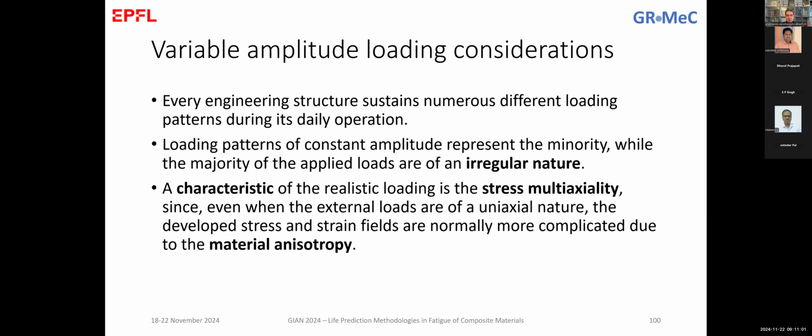And the question is if we can use this failure criteria for this kind of conditions as well. And of course, when we talk about anisotropic materials, we know that even uniaxial loadings can lead to multi-axiality in the stress fields.